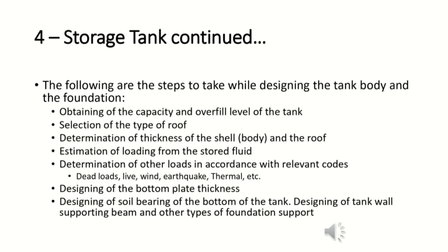The following are the steps to take while designing the tank body and the foundation. 1. Obtaining the capacity and overfill level of the tank. 2. Selection of the type of roof. For example, for storage tanks, the kind of roof that will be used is of different types. There are fixed roofs and there are floating roofs. It all depends on the kind of product that is being stored and some other reasons that you select a particular kind of roof.